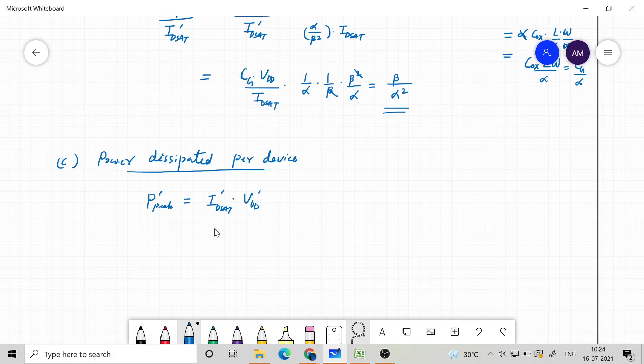Okay, so in some form or other it will be reflected in the other power, like the dynamic power, like charging the load capacitor or parasitic capacitor through the PMOS. If VDD is different, that will be different, and then the ID sat, so it will give an estimate. Similarly, short circuit power also depends upon VDD and the short circuit current.